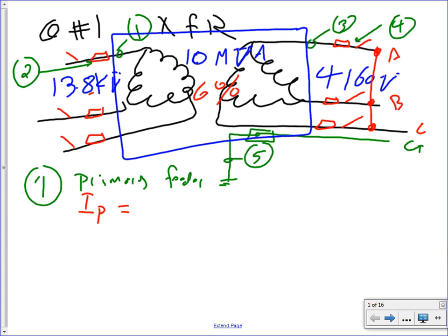Do you see any windings connected to the ground? So are you attaching the ground to the transformer itself? Yes, the frame. That ground, the ground bar, is just grounding the frame of the transformer and the conduits. But do you see the windings themselves? The wires, any wire connected to the ground? No. The conduits and the frame, the box.